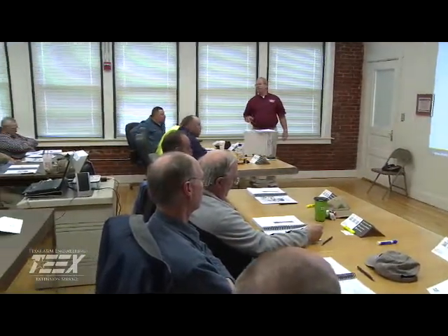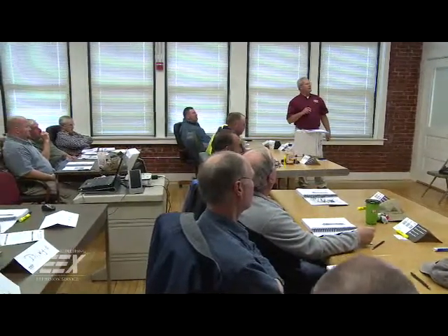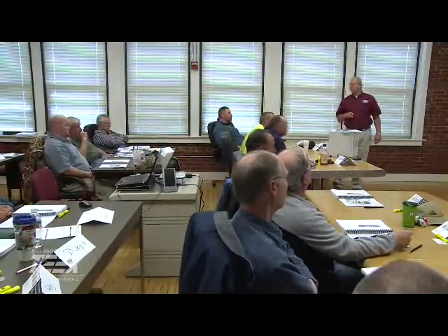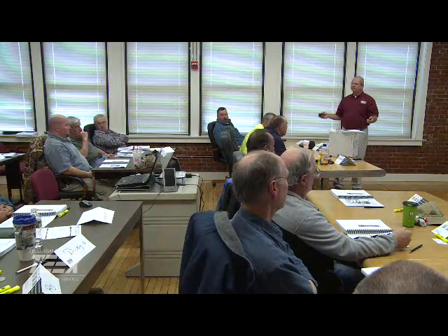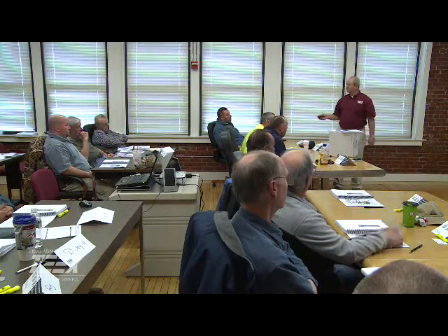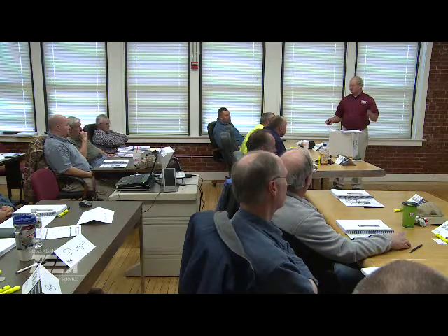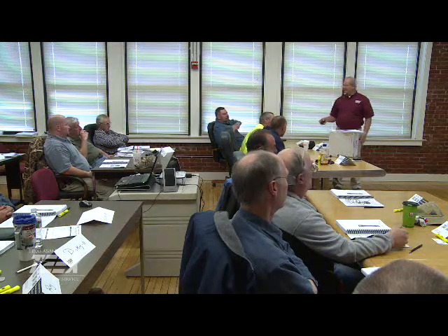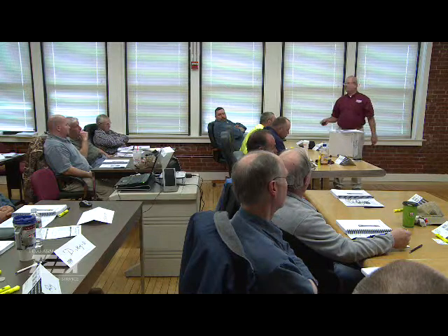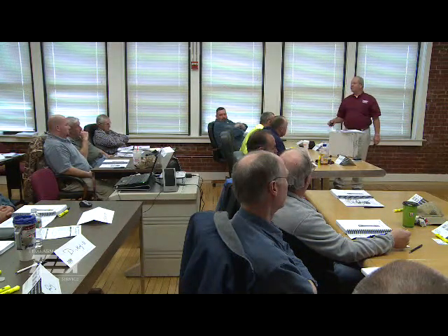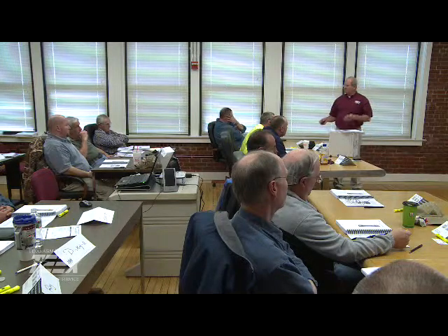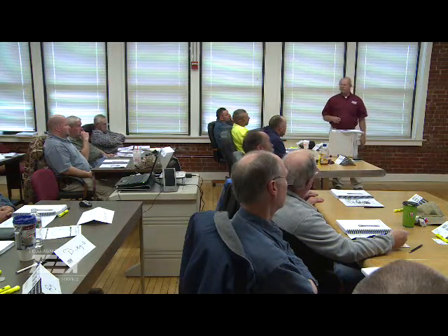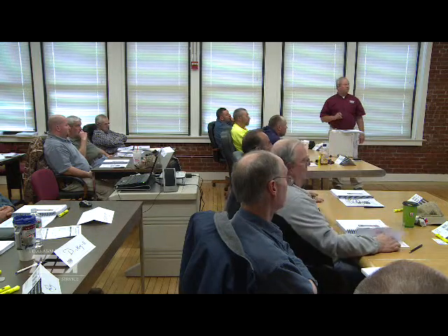And color coding, if you're following AWWA, the bonnet is what must be color coded. And do y'all follow AWWA on your standards? Red is less than 500. Orange is greater than or equal to 500 but less than 1,000. Green is greater than or equal to 1,000 but less than 1,500. And anything greater than or equal to 1,500 gallons per minute is color-coded blue. So that's the bonnet, must be color-coded. That's AWWA standards. That's not a state standard, that comes from the AWWA and the fire people.